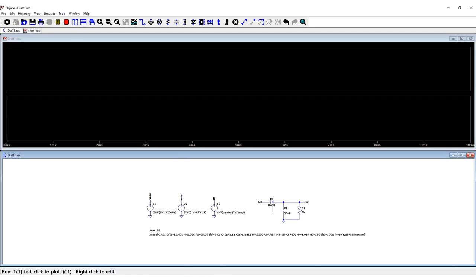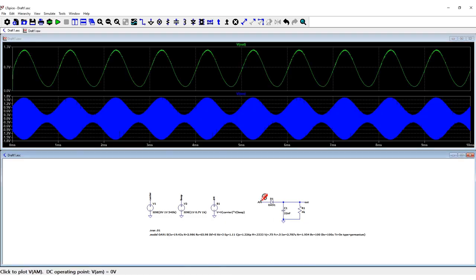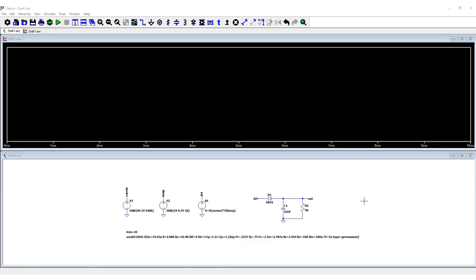First, without explanation, let's take a look at the demodulated signal. Okay, it worked very well. The input signal of the envelope detector was an AM signal, and the output is the information, in this case the beep. Now we can explain the parameters. For example, why do we need to use a 22 nanofarad capacitor, or what does the diode do?